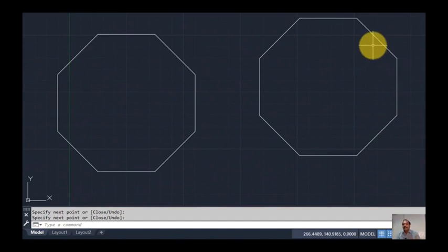Like this I added. I don't want to calculate in such a way. Why? Because if I make any mistakes while calculating the angles, then the polygon will not come properly. 8 sides, adding 45 degrees, that is not an issue. We can draw any number of sides, 10 sides, 20 sides, 25 sides. During that time, if you go for adding the angles, you may miss any one angle.